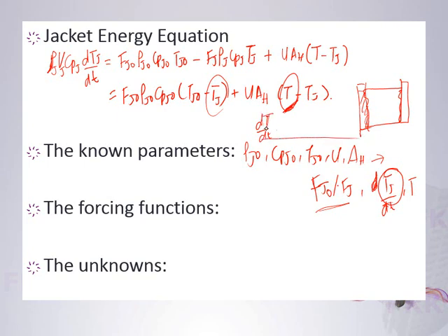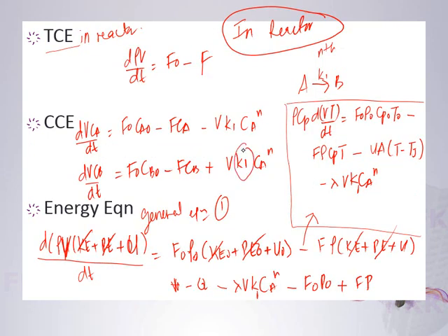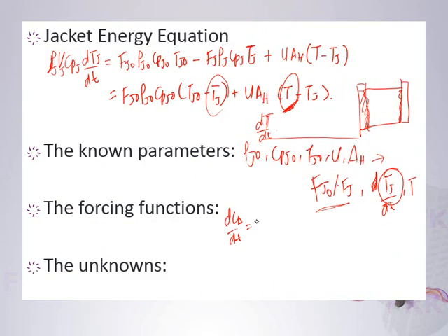In order for you to solve your dT, you have to solve your CA. Remember? Because in your dCA on dt, you have the value of K. What is the equation for K? So this is actually a function of K. This is the Arrhenius equation. So your K is actually A exponential minus EA over RT. Remember, in order for you to find your CA, it is very much depending on your temperature there.